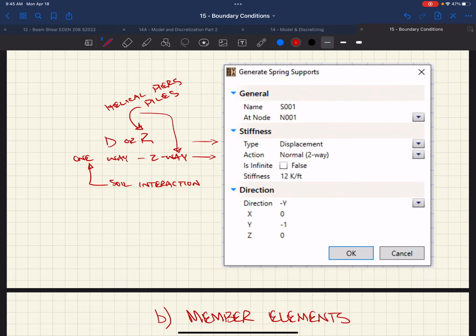You're not talking just like all of them directly drilled down. They do still have some of that resistance. But then I would say for very small loads, I would probably feel comfortable with just doing that, right? And looking at maybe cantilevering some of those posts of the helical piers. But you're talking helical piers, right, or piles? Yeah, helical piers, right? For helical piers, you just start drilling at an angle. Have you seen that before? Yeah, you do tie back, because they're such slender elements, you know, if you need actual lateral resistance, you have to batter them for it. So you just put them at it.